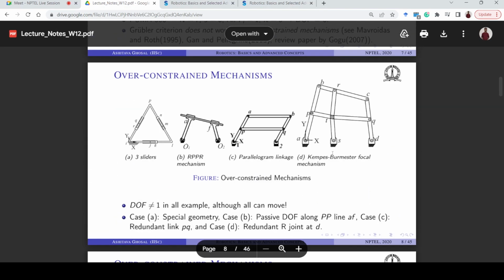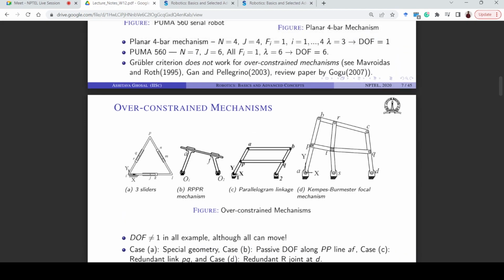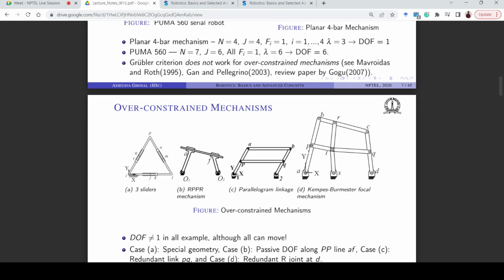Okay, so this is the Bricard-type mechanism. So this is again an over-constrained mechanism, and you can see that there are many links and many joints. But they are interlinked with each other. So this particular joint T is a common joint for four different links, right? And most of the joints, like this Q, the C, and B, have multiple links attached to them.